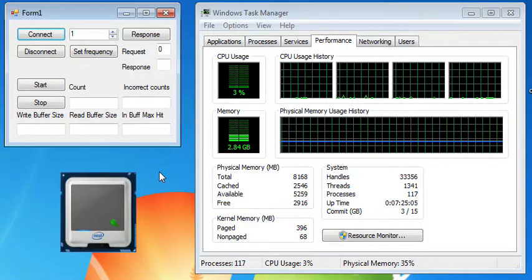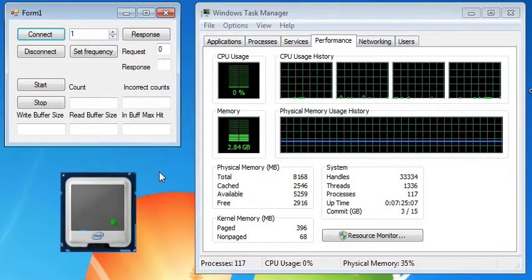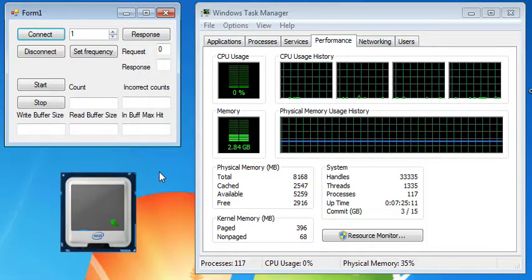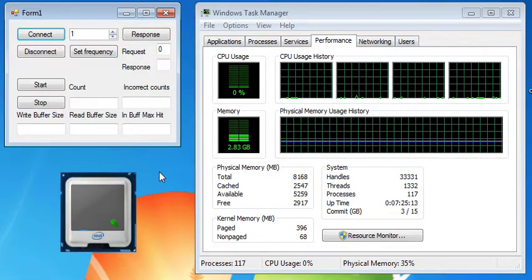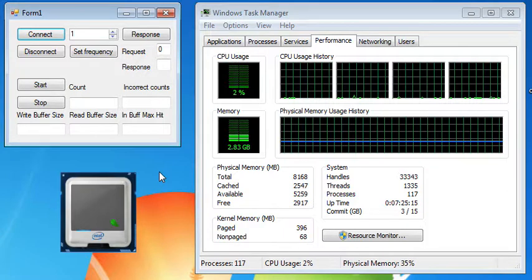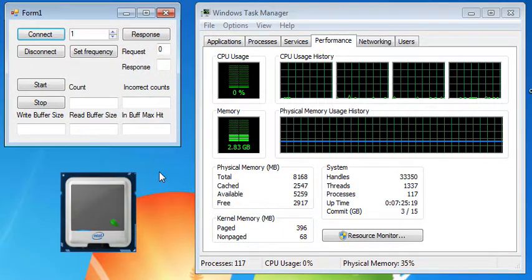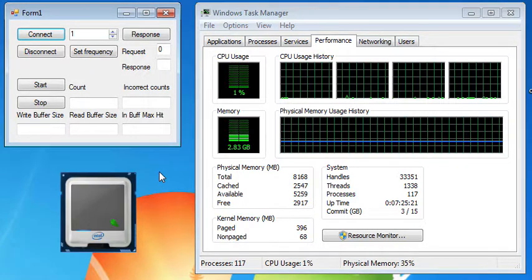In this test at low frequencies, you may notice the in buffer is always roughly 3 to 5 bytes. However, you also notice that when the speeds begin to increase, the buffer length grows. This shows that by the time the event thread begins, many commands have been received. You should also see the processor clock speed and usage increase at high speeds due to the for loop run to process all our commands.